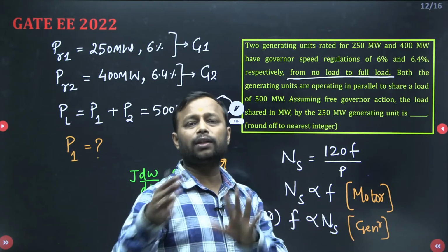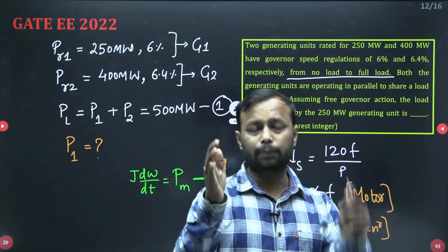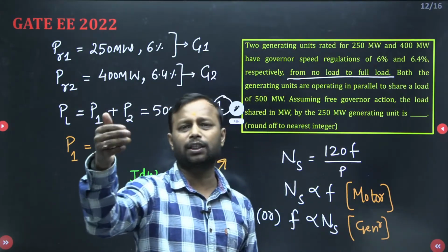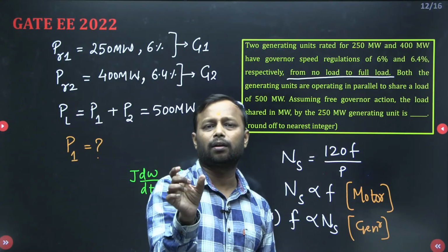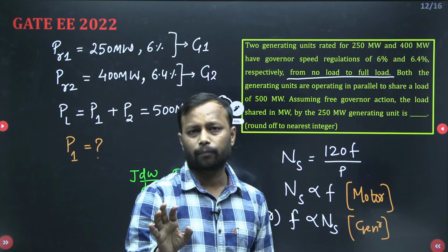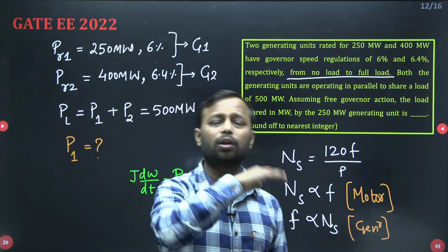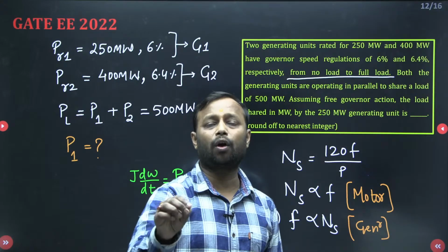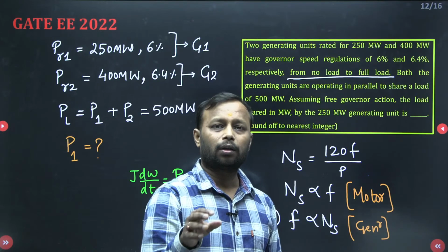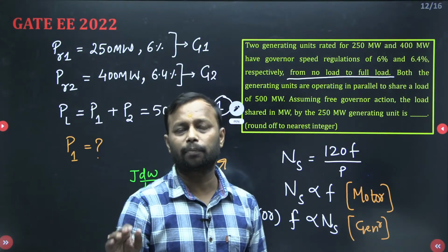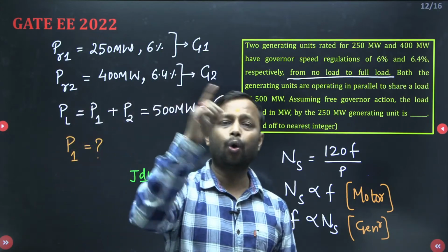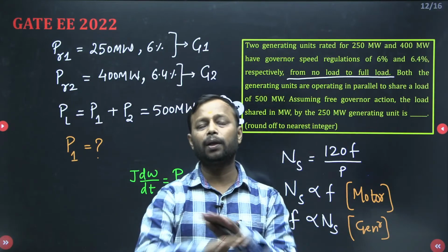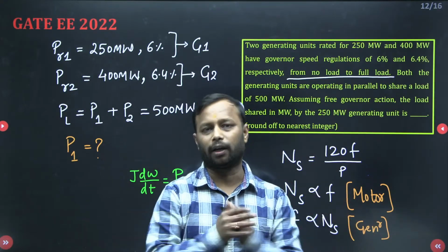Once the frequency reaches the specified or safe limit, which practically, suppose if the no load frequency is 50 Hz, then the safe limit is 47.5 Hz. If the frequency goes beyond 47.5, there will be a situation of blackout. What does it mean? Power grid failure. It means the whole electricity of the state is going to be off. There will be no electricity in your state.